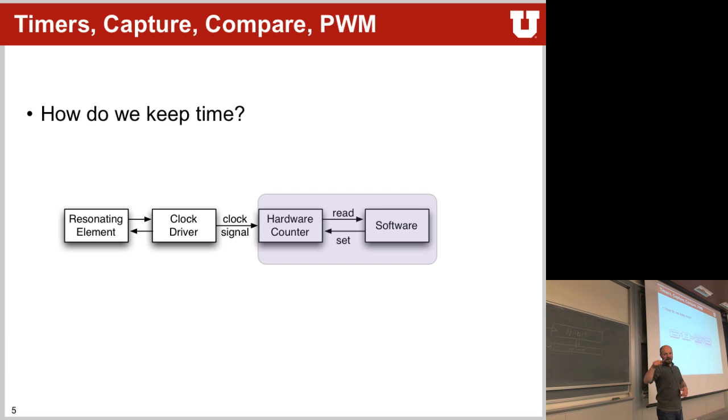Assume you have a wheel that turns, and every time it comes back to the top, it will give you a signal like this, right? So now, using your counter, you capture twice the time it took. So the first time when you're at the top, and then again when you're at the top. So now you have 2 times. You subtract one from the other, and then you know how many counter clock ticks you had between the wheel going once around, right?